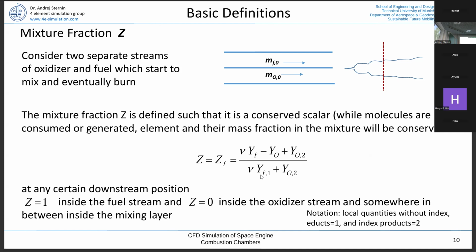Then we may have some turbulence, which helps mixing, and then we get a finite flame thickness. The more sophisticated models now say that, in order to be really predictive, we need maybe 2 or 3 or 5 computational cells within the flame thickness. When we do direct numerical simulation, we try to have maybe 5 or 6 computational cells within it.